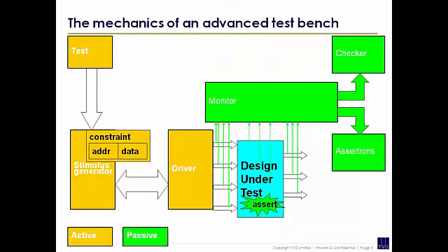Okay, now what? If you look at why, at the moment, that is a test bench that can just run by itself, because this is constrained random, effectively you've got random data constrained in some way. Every test you run will be slightly different, as long as it's got a different seed. So in the random environment, each test will have a seed which is maybe a 64-bit number. So the chances of repetition are tiny. So there's going to be no repetition, and you just keep running these tests, and it will run a different test every time. Okay?